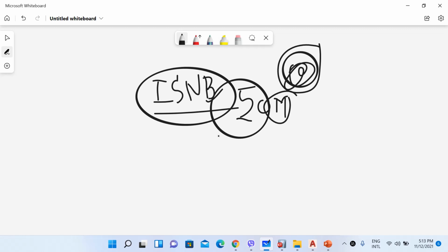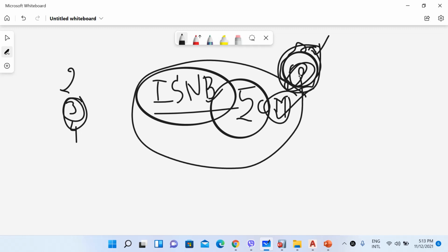This 50 mm diameter tube section also has different thicknesses. If you have this 50 mm diameter tube of 2, 3 and 4 mm thickness, the middle value, 3 mm thickness, is known as the medium weight. So we will represent that by M. So this is how you represent a steel section.